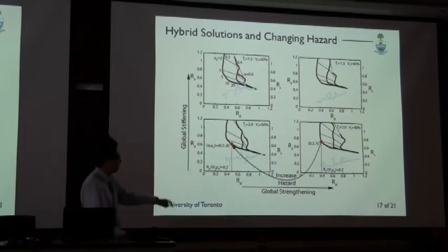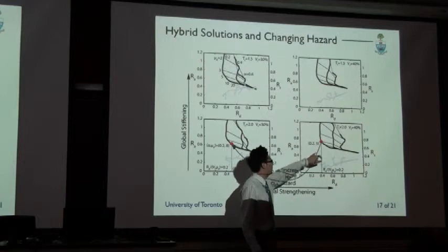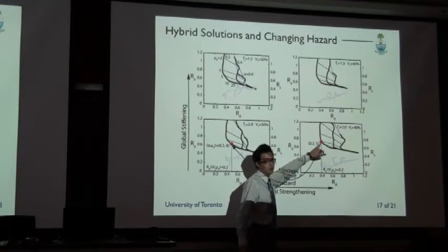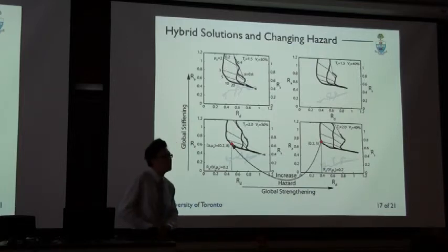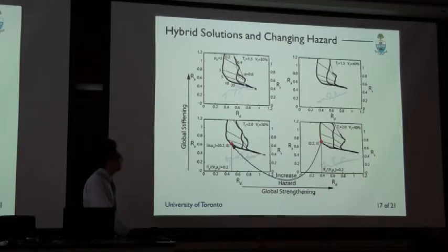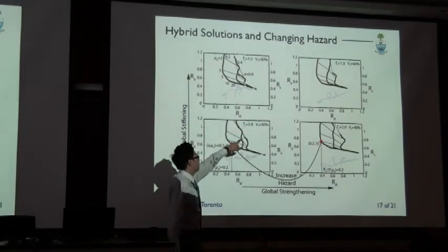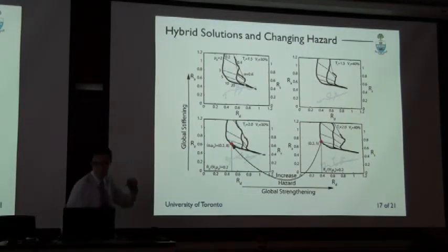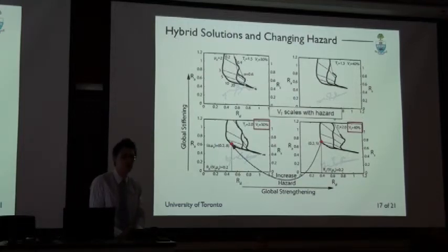Also, let's say you have a base hazard level and you selected the solution at this point, the spectra of T equals 2 seconds and strength of 40%. And you wish to consider a higher hazard, which often is the case. All you have to do in the performance spectra matrix is to read off the response at a lower normalized strength. The reason for this is that the normalized strength is directly inversely proportional to the increase in hazard.